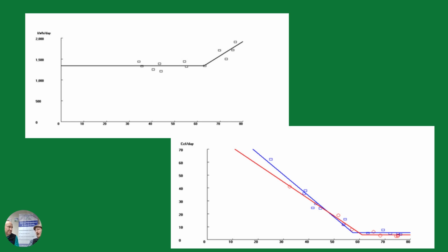So I always say that, and I guess maybe I'm inferring that everybody likes Excel as much as we do, but being able to throw numbers in Excel, you can build some pretty simple but also some complex graphics. And we also use some other software tools. This one gets into what we call a multi-point regression, and that's really just engineering nerd speak for taking the utility data at the meter, and it could be additional data points, but typically we're taking it at the meter and saying, let's graph that compared to the weather trend. Based on it getting warmer or getting colder, what does this utility meter look like?